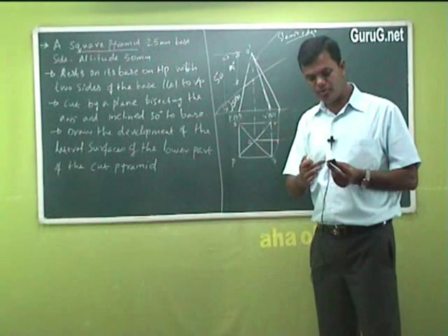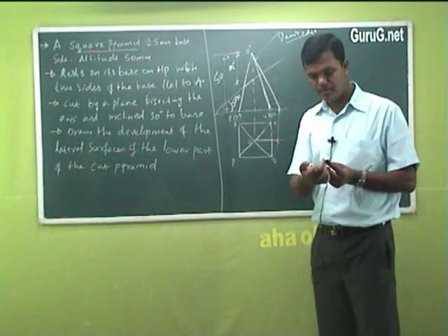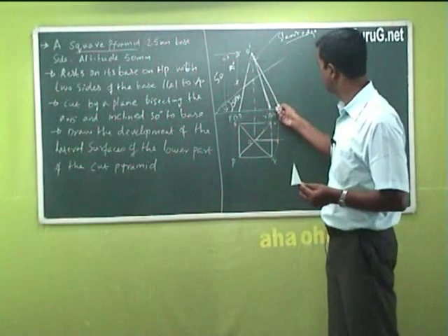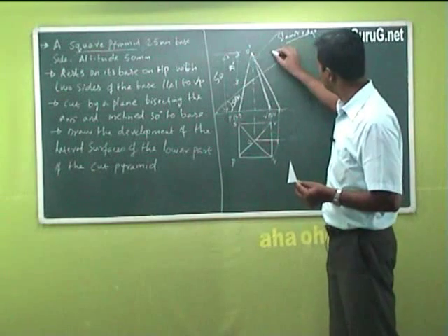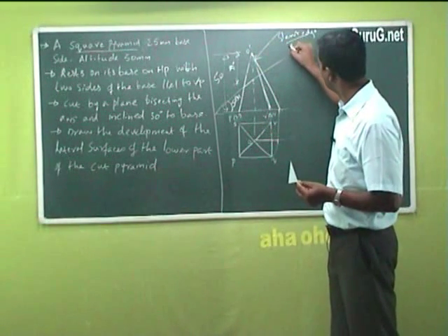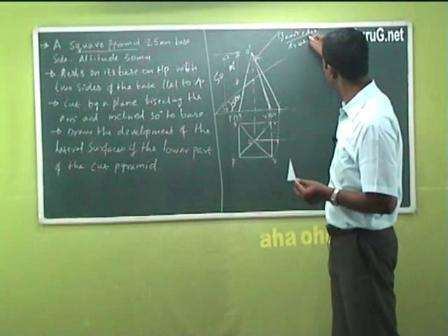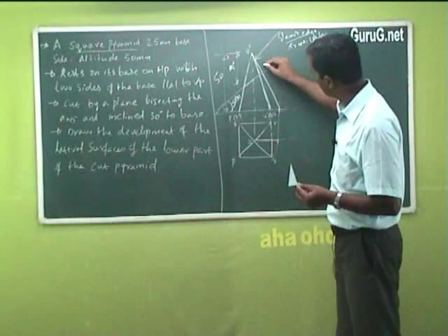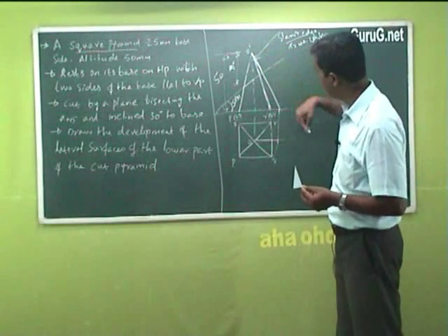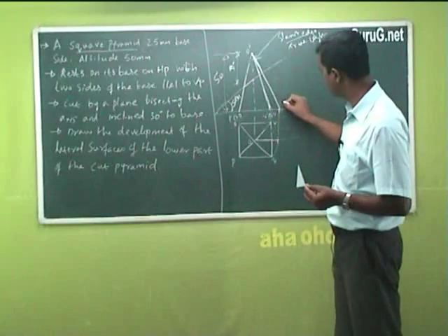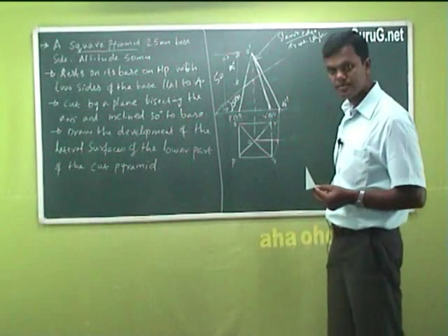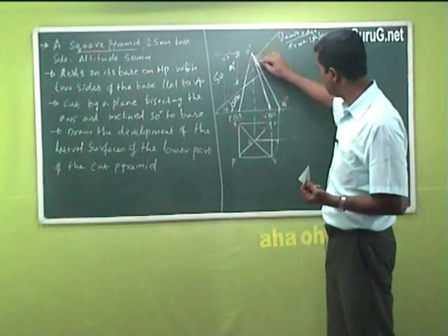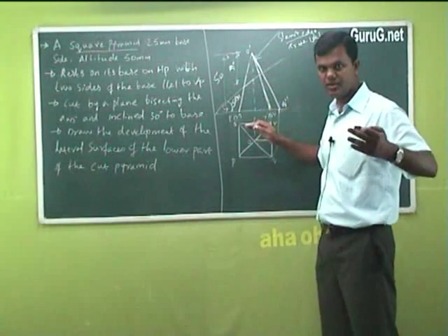That means this corner you made straight by bringing it to the center. And from the O point, that is a line that you should join with the top. So this you are joining to the top. This becomes the slant edge, true length. The second line is the slant edge, true length. I'll call this point Q double dash. This point Q, Q double dash or Q dash. So this is the length you require for developing the pyramid.